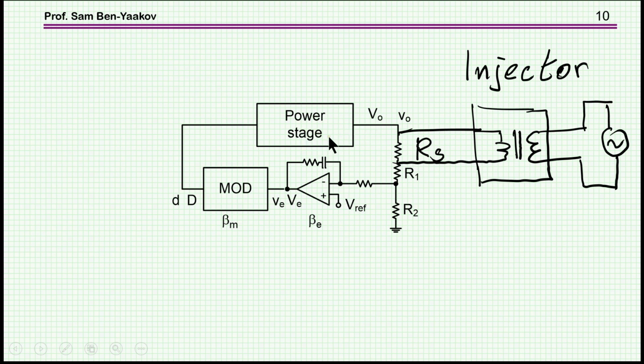Well, if this is a power stage, then obviously, say if it's a buck, you have an inductor and a capacitor. So you see here basically at high frequency the capacitor. So this is the impedance we are talking about, okay? So the measurement will be correct when this capacitor shows a high impedance, that is high frequency, and this is when we have the crossover. So everything is okay if you are connected here to the output capacitor of the converter.